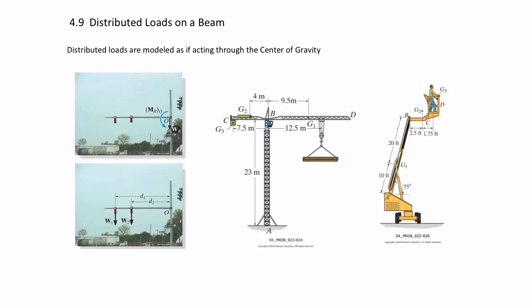How about this crane here? We've done this crane a little bit. Over here on the left hand side we have that weight, and we're going to model it as a point. This one is going over this way, but we're still going to model it as a point. That might make some sense because they're distributed over some distance, but their weight can be assumed to be concentrated at a point. Over here on the right hand side we have this load, which is clearly not a point mass. However, because the tensions are going up here and right here, we can say that the entire weight is concentrated right there, so that when it pulls down it acts as a point.